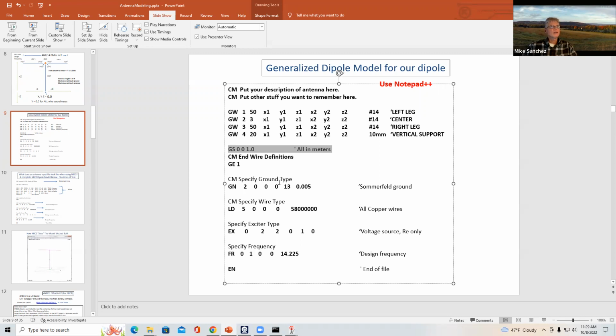However, when you start doing frequency sweeps across an entire band or multiple bands, let's say you build an antenna and you're going to scan from 2.6 megahertz all the way up to 30 megahertz, then you're going to run 256 different slices with 4NEC2, and this additional little bit of mathematics takes a lot of extra time.